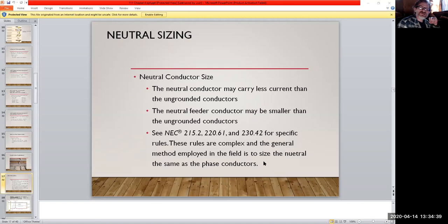But yeah, you can have the neutral conductor be on a smaller gauge than the hot. Rule of thumb is usually, you pull the wire through, and you got like number 14 traveling through a branch. Your neutral is going to be number 14 as well, but it's not unheard of that it could be like a number 16 or something like that. So if you do see it be a little smaller than what the hot is, that's not allowed, I guess you should say. But the NEC does have specifics. You have to be careful, right? Continuous duty, that kind of thing. You're generally not allowed to undersize, but for certain situations you could.